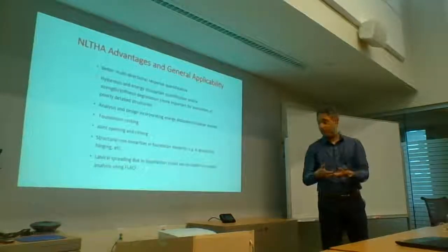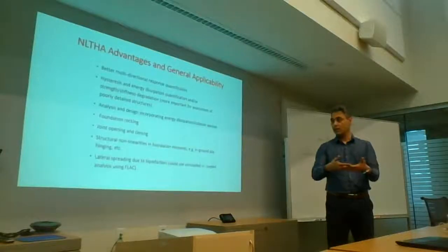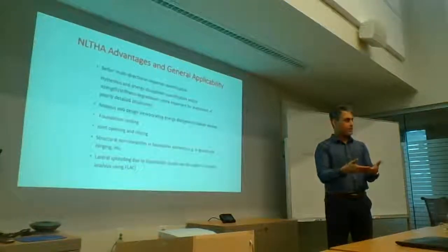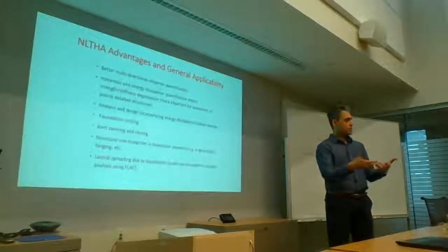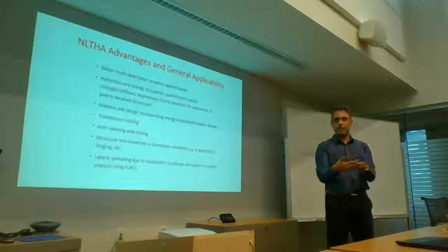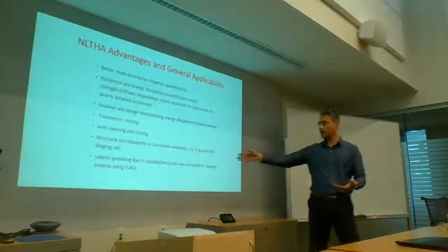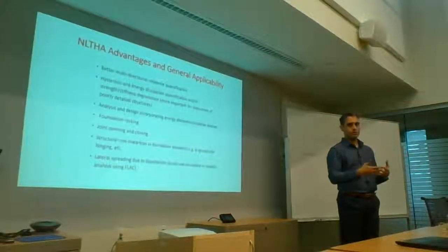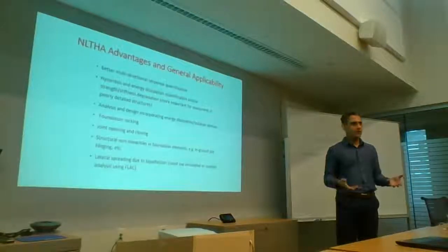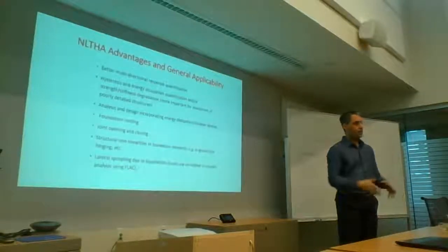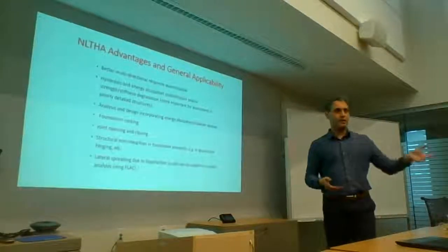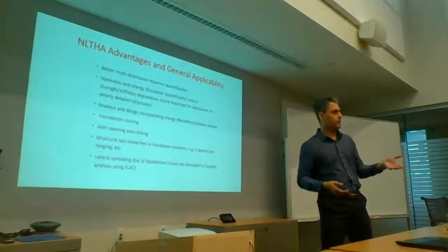But what really happens in real life is the soil behavior changes. So the piles and the soil interact with each other. So when you're running an uncoupled analysis under free field conditions, you get one answer. The soil might be moving 500 mm. But now if you run it with the piles, it may be 400 mm, or maybe 100 mm.